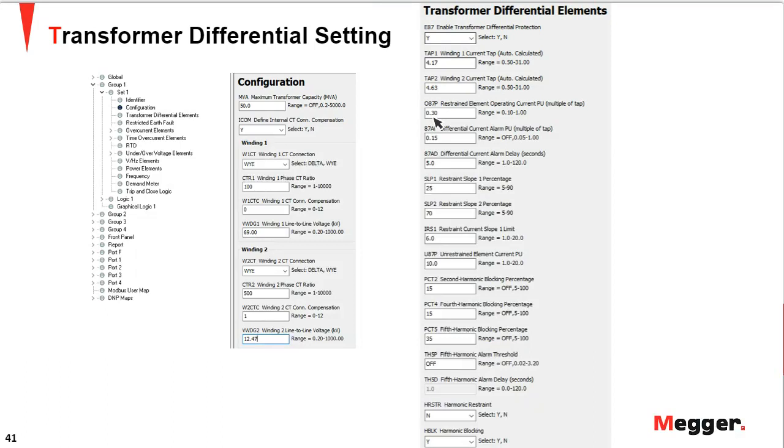So all these account in defining the 0.3 PU level of the minimum pickup. Everything related to CT accuracy, CT mismatch, and all the steady state errors define that level. So it could be anything depending on the transformer that is in place or the system it has been used at.